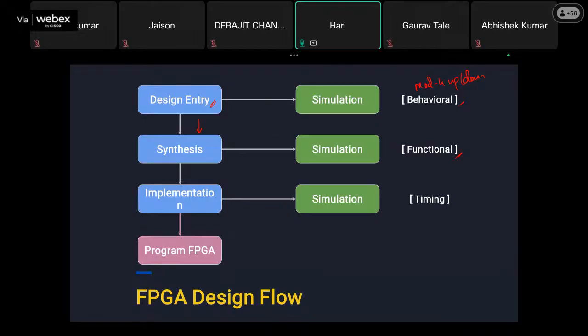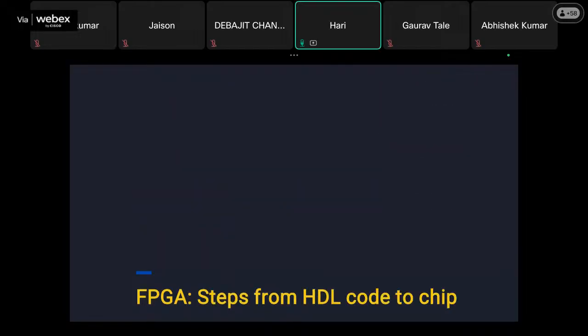And then apart from it, we will have implementation. Implementation in the sense of placing, fitting, and then connecting. Place and fitter is there, then interconnection should be made, and then the LUT mask should also be programmed, right? Those things are also done using implementation. And then we can verify timing based verifications as well. If you wanted to execute one particular function within a particular time, you can check whether you can do that. Okay. So at the end, you can program the FPGA using bitstreams. We will be going through that very fast.